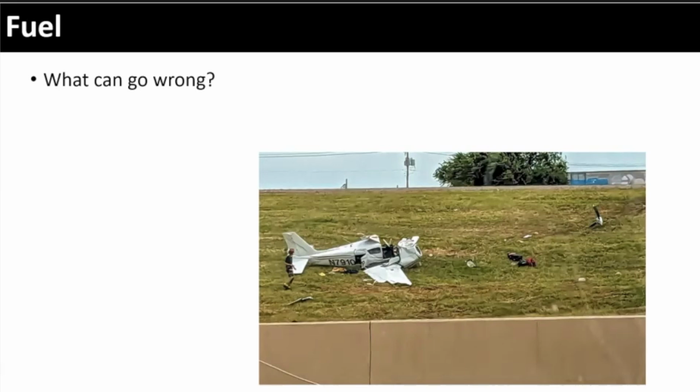It's not likely to happen here because we've got the jet fuel and the 100LL, right? So you're seeing the big truck pull up in front of your plane or the little truck. If the big truck pulls up in front of your little plane, that's a flag. Say, stop, don't put that in my airplane. But that doesn't say it couldn't happen, right?